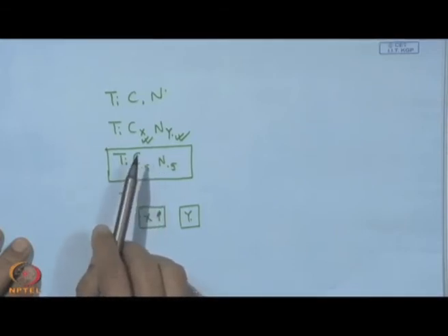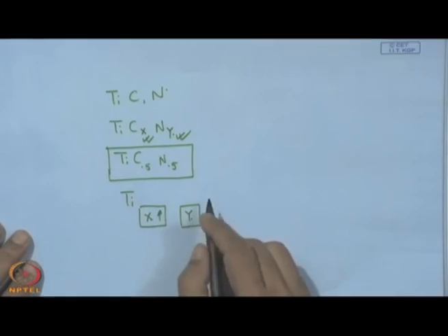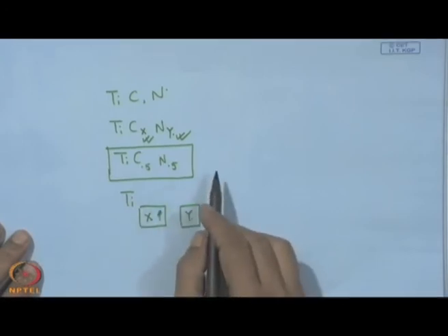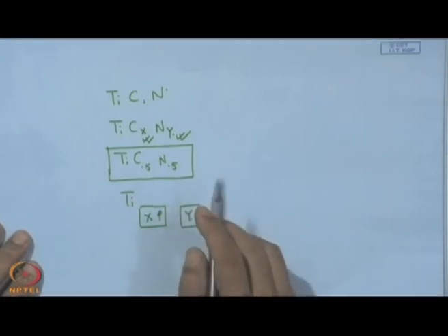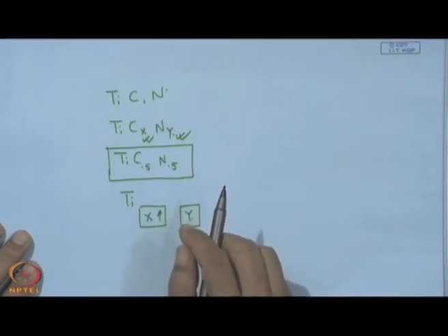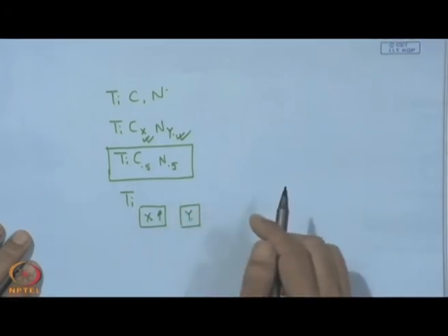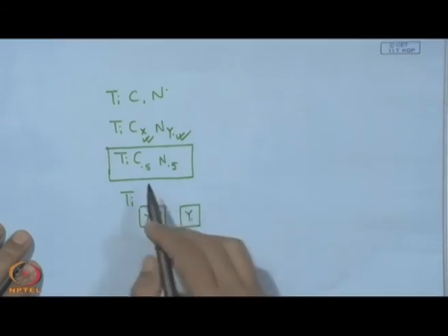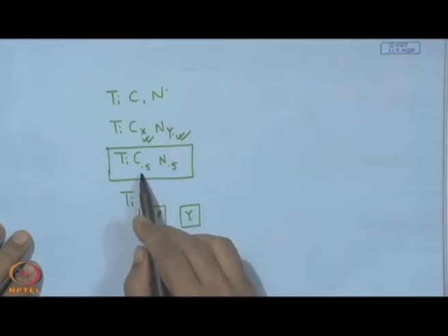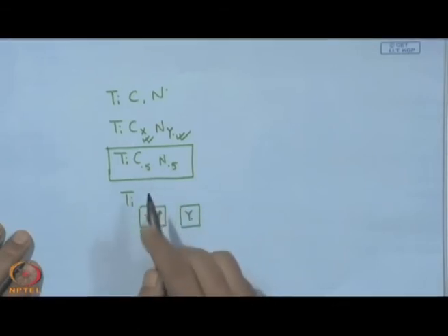This is also another experience, that with slight increase of temperature of deposition, hardness of the coating also increases, and this can be explained by the higher concentration of carbon in this coating, because titanium carbide is basically harder than titanium nitride.